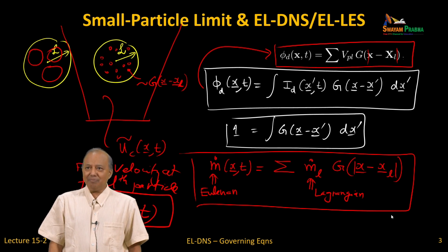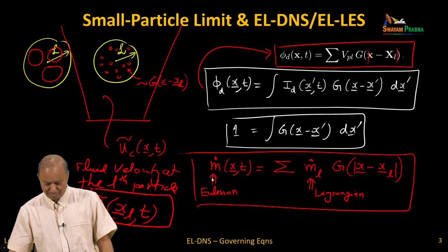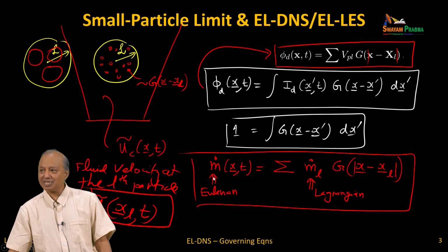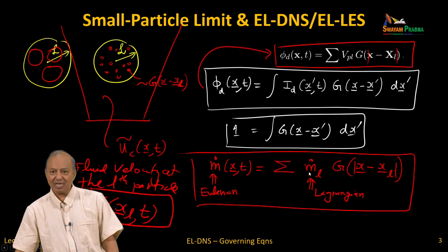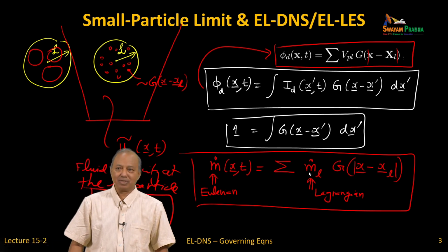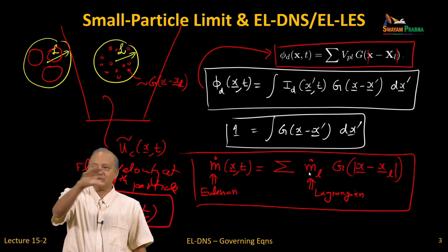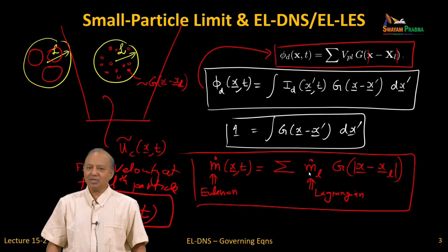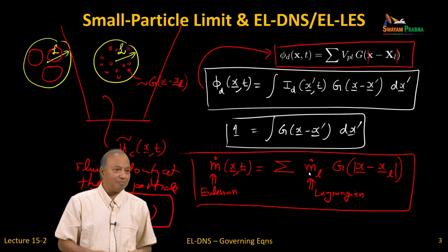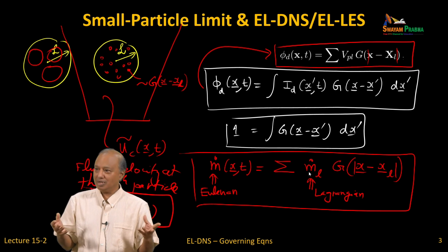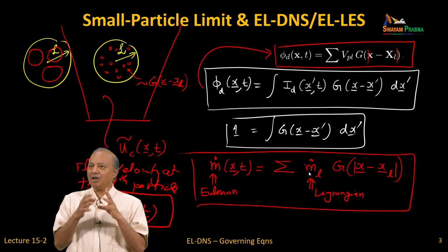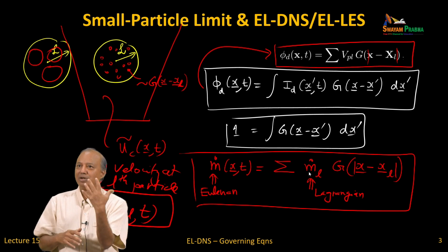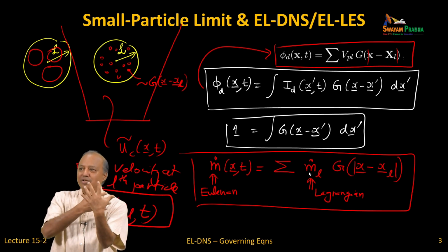Where does that m dot for the whole cell come from? This is m dot for a cell, whereas all you have is m dot for individual droplets. So you are doing a Lagrange simulation, you have a bunch of droplets, your cell has 10 droplets, and you know the evaporation rate of each droplet from your model. You have to now convert. This is what I was talking about earlier, that you have to couple the Lagrangian with the Eulerian.